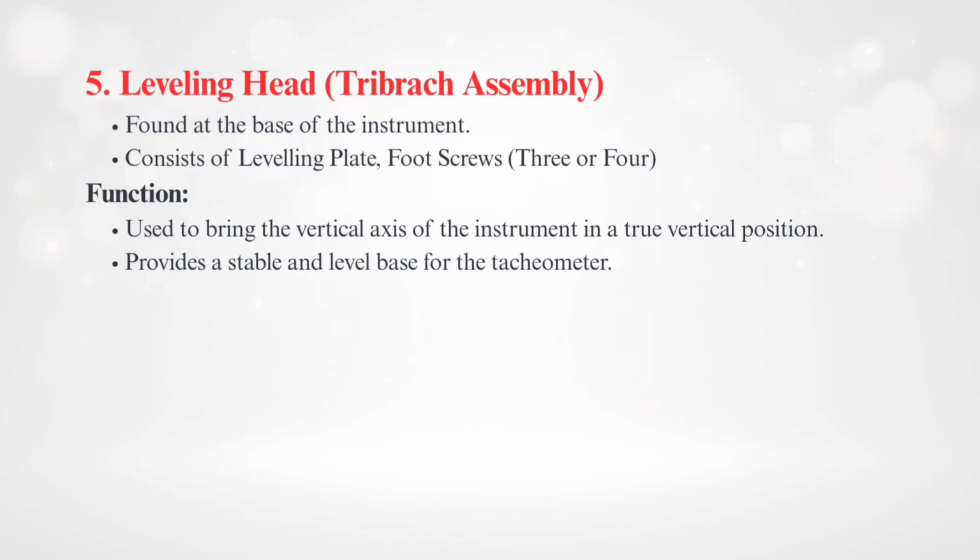Then the next one is the leveling head. The leveling head is present at the base of the instrument and consists of a flat leveling plate and 3 or sometimes 4 foot screws. By adjusting these screws, we can make the vertical axis of the instrument truly vertical, and this provides a stable and level base for all the measurements.